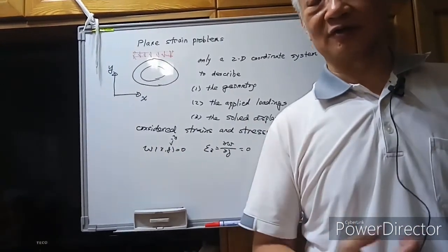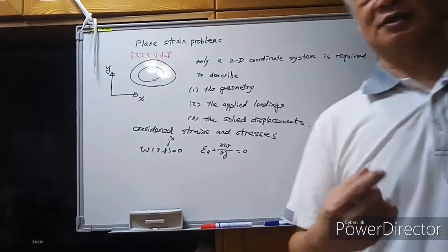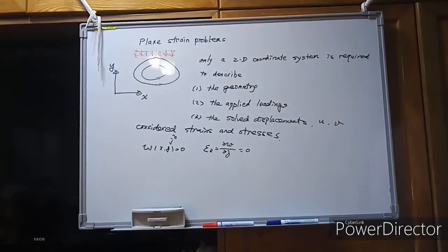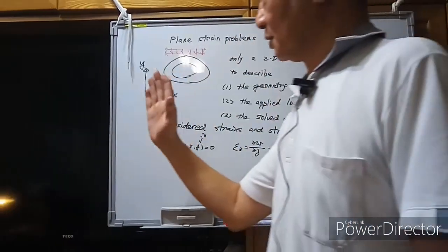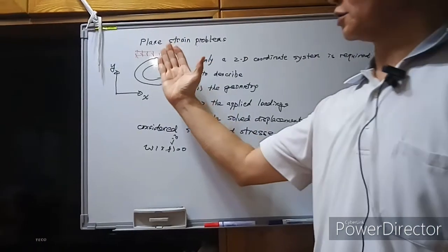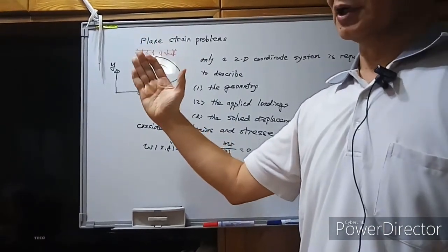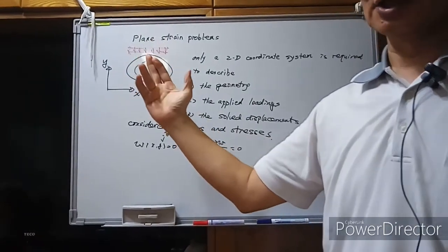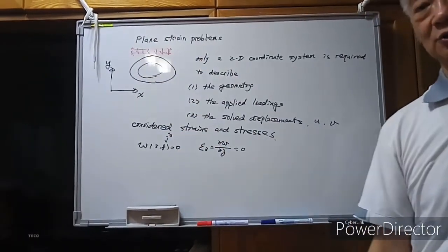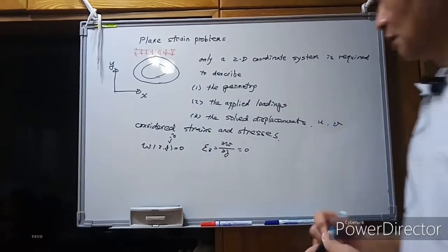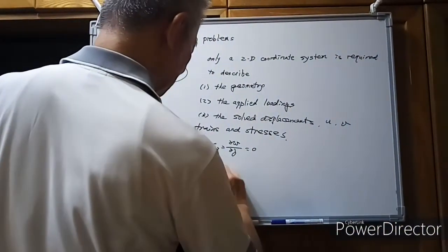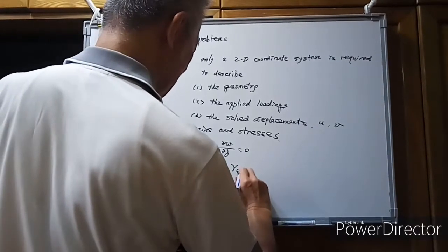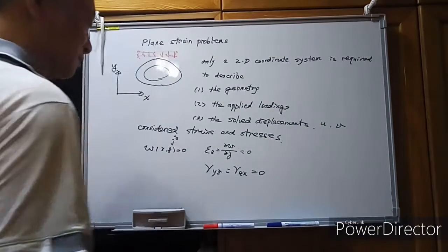If you take a derivative of a constant, the derivative must be equal to 0. Okay, also it is not possible to have the shear strain, since if you got a non-zero shear strain, you would still have displacement. So also for the gamma yz, all equal to 0.